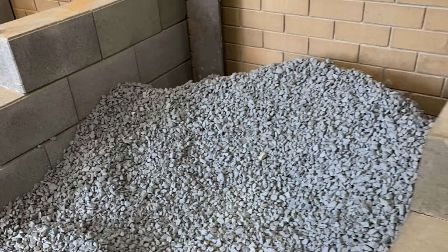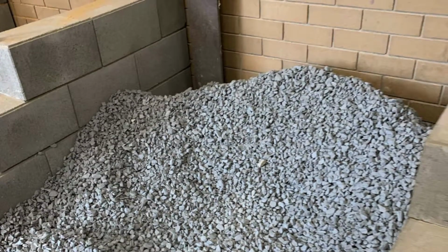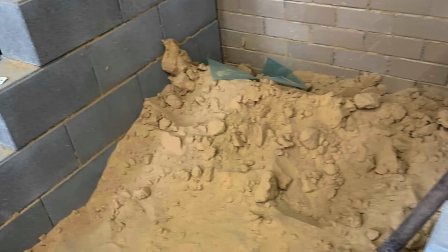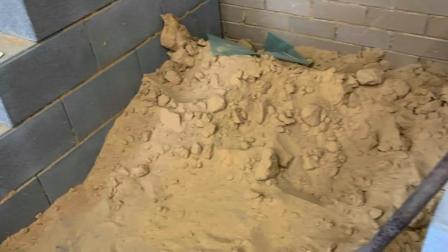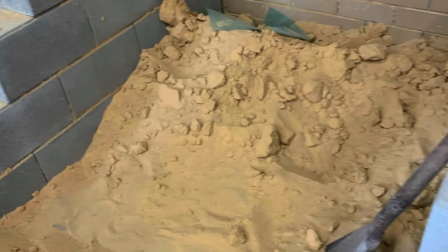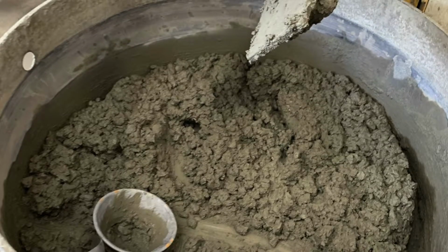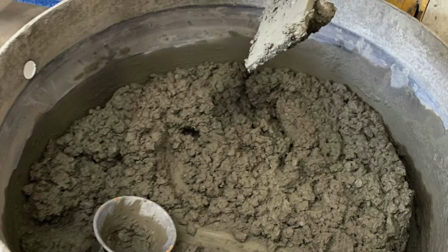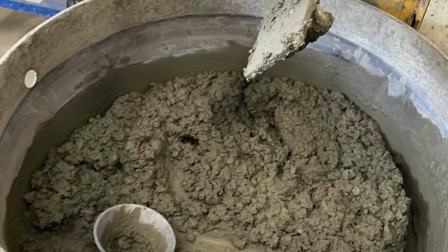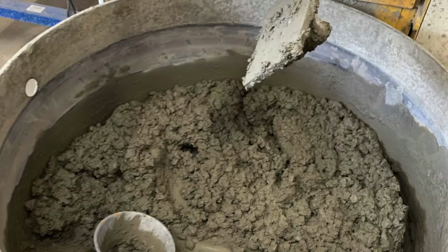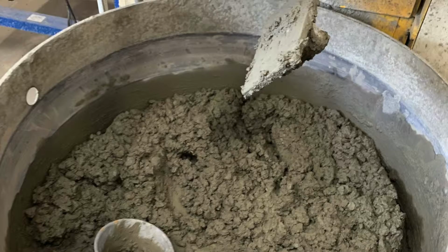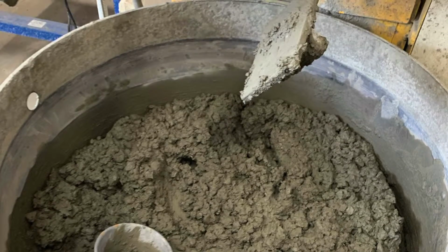At Mawson Lakes, we visited the L building, which is extremely similar to the one that we will be designing for this project, so it was very useful to be able to see the design processes having been used on a superstructure in person. The site supervisor pointed out that perhaps the purlins are spaced too close together. Although this is not a structural issue, it would suggest that the building was not quite as economical as it could have been.